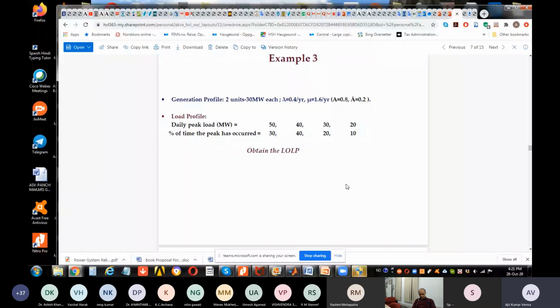First, you have to relate these components, units, subsystems to the system, and then define their functions, then find out their role and criticality in bringing about a system level failure, and then initiate corrective and preventive measures by which you can make the system more robust. At least that's the way I think from an industrial point of view.